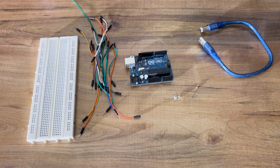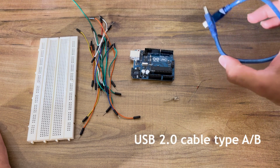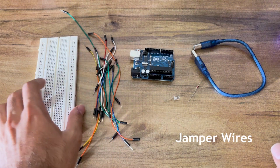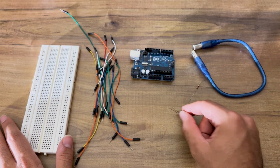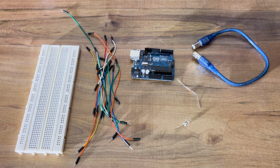Okay guys, for this session, you have to buy these things. As you can see, I bought Arduino Uno. I bought a cable that I can connect Arduino to my PC. I bought wires and one breadboard and one LED. The color isn't important. And one 220 ohm resistor. Let's go to wire these things together.